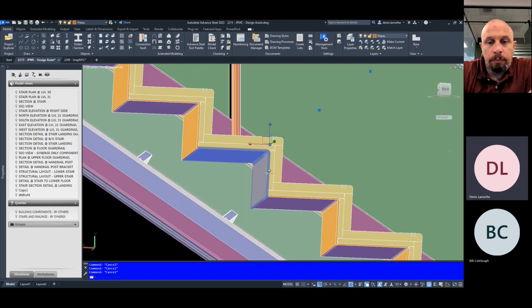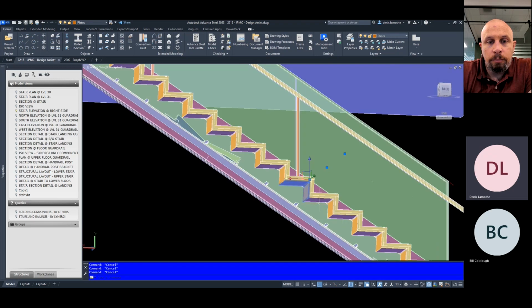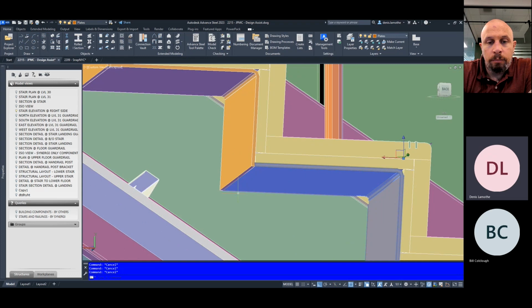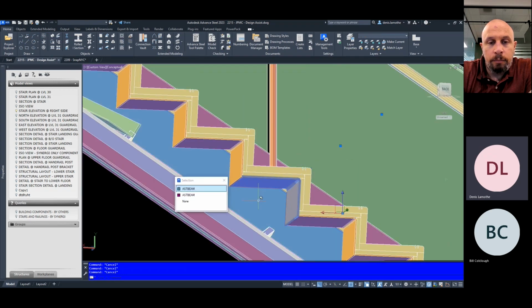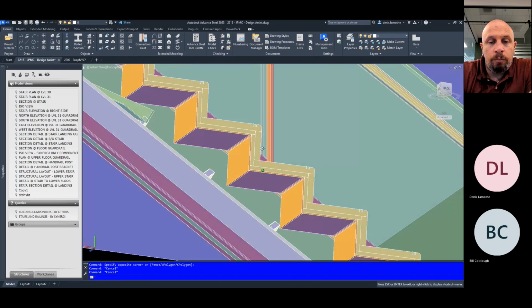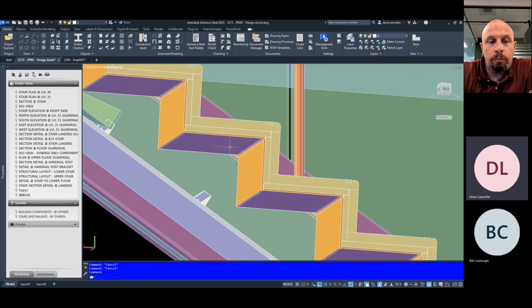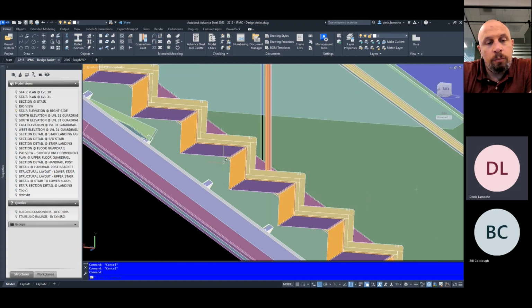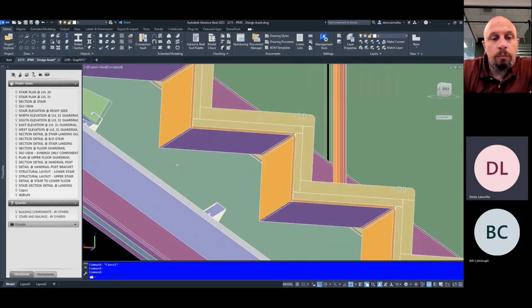The advantage of that is that we can create one part and just copy it multiple times, as many steps as we need. They're welded straight to the stringer, or the stringer may need to be what's called a sawtooth cut. This is where we notch the stringer so that the treads and risers sit on the cut edge. They sit on top. And so having a form plate also allows us to extend beyond the stringer if we need it, with that saw cut in the stringer.